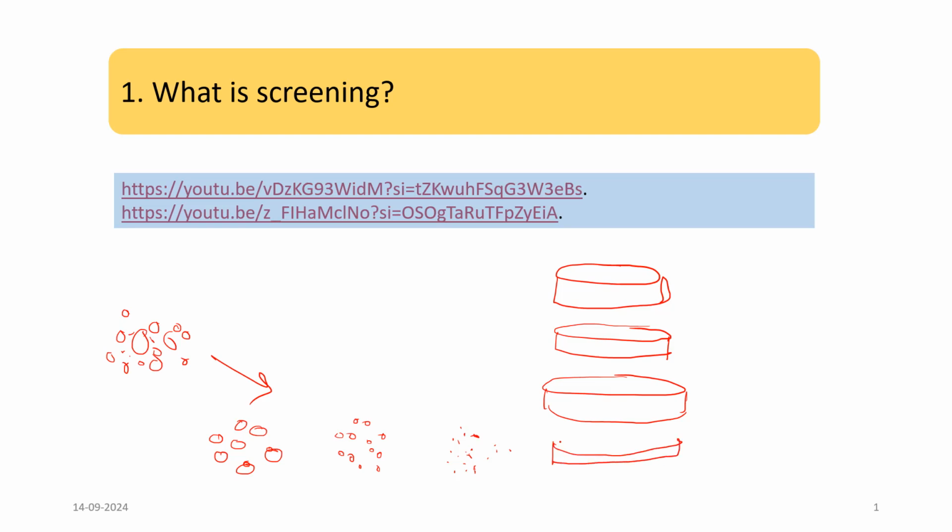This final sieve is called the pan, where only the underflow particles remain. Screening is accomplished by passing the materials in an open cylindrical container with uniformly spaced openings of the desired size at the base of the screen.